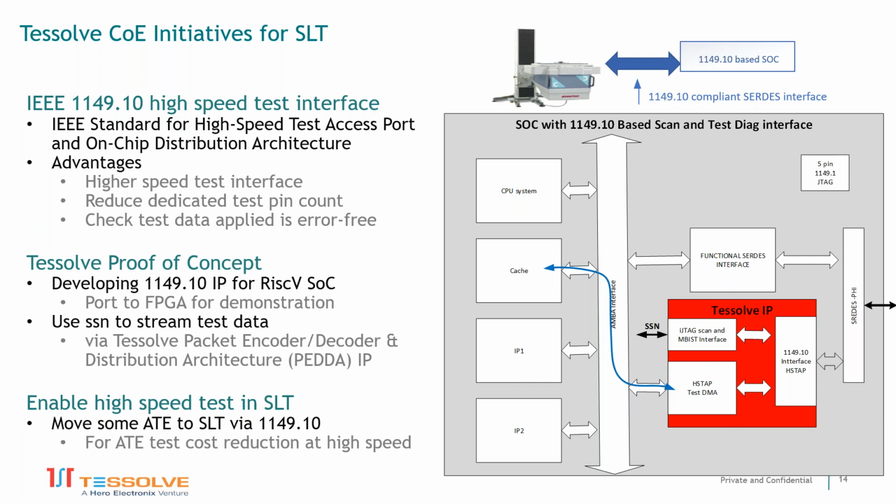I think it's a format from Siemens. I always think of Mentor, but of course it's Siemens now. But it allows you to packetize those structural tests, if you like. Normally those tests would just be run across the JTAG as a scan chain. But as soon as you start pushing them across a USB interface, obviously the format has to change. Okay, thanks. And that's what SSN is there for, that format change.